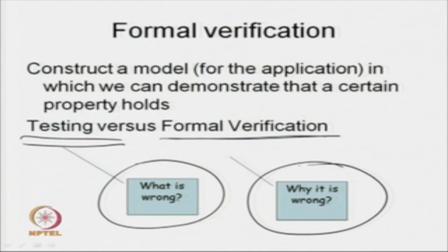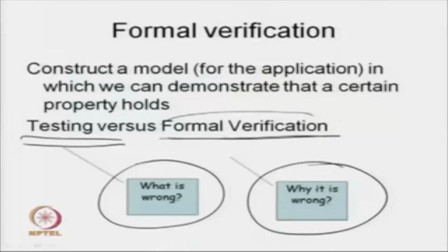So, after the design phase, we do the verification, and in verification we give feedback on why something is going wrong. When the design team gets this feedback, they can revisit their design, fix the bug or error, and come up with a new rectified design. With this new rectified design, we again apply verification, and when we are satisfied that it is satisfying all my properties or requirements, then we proceed to the next phase. Basically, the next phase is implementation or fabrication.